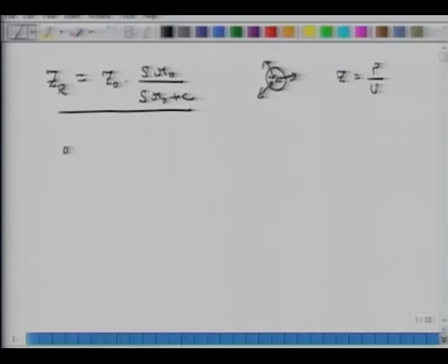In other words, if I have a pressure applied here and a black box which can constitute a group of different resistive, inductive and capacitive elements, how will this network look so that the impedance offered by this network is equal to this? That is what we are trying to figure out, because if we know that, then we can put those resistors, inductors, capacitors in the whole circuit and solve.